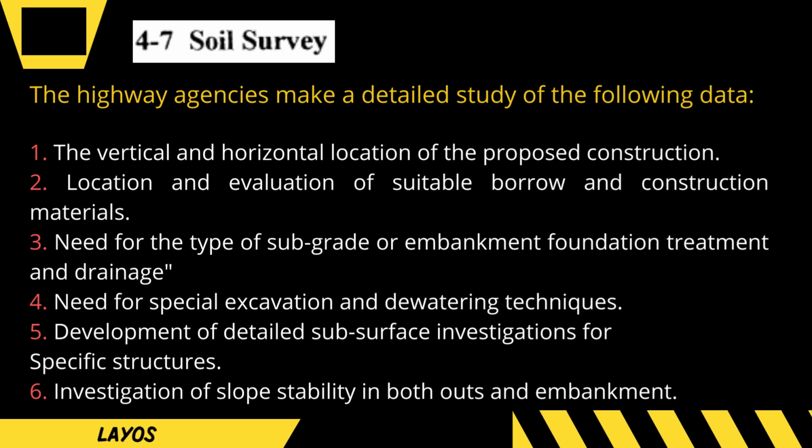The subgrade course is typically the natural soil as well as chosen particle size aggregate which is compacted to specific levels. An embankment refers to a volume of earthen materials that is placed and compacted for the purpose of raising the grade of a roadway or railway above the level of existing surrounding ground surface.